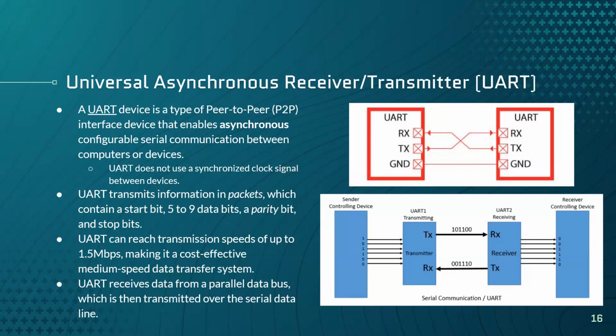The actual information it contains is sent in packets, similar to the packets that are sent over a computer network, if you know computer networking. They have the start bit. You can think of the start bit as like a 0. In I2C, 0 was the start bit, because when the data sees 0, it knows that's when the communication will start. Then the data bits, and then the parity bit.